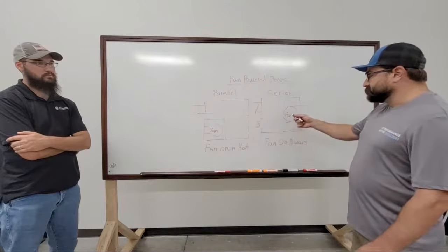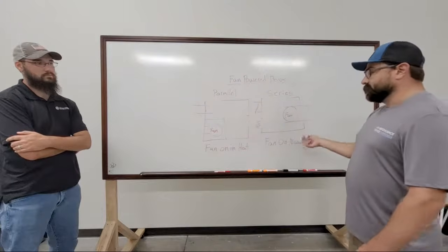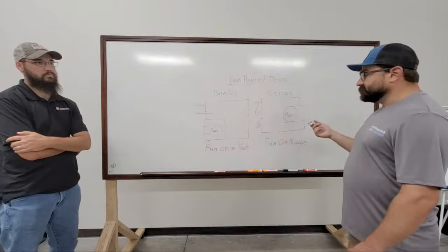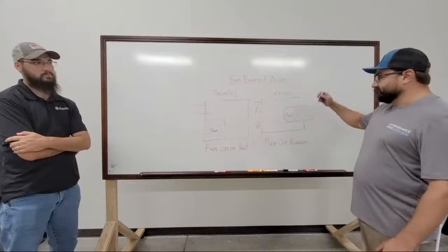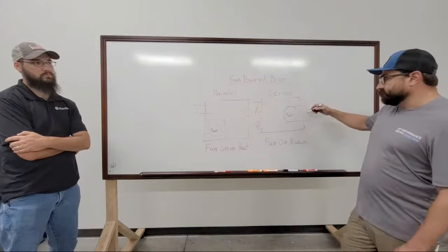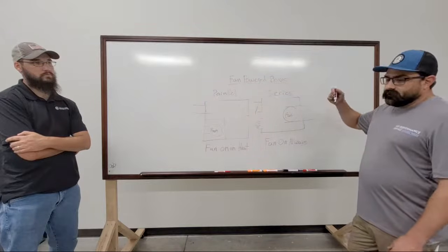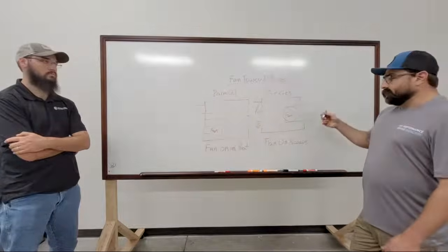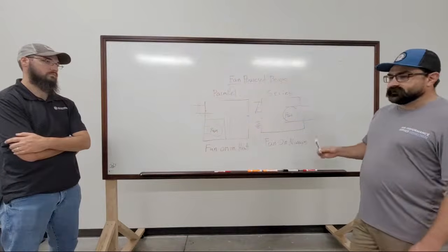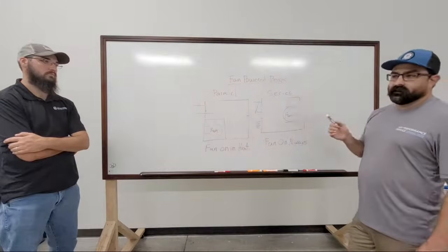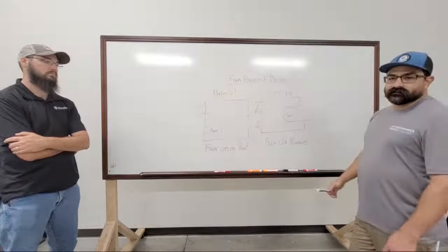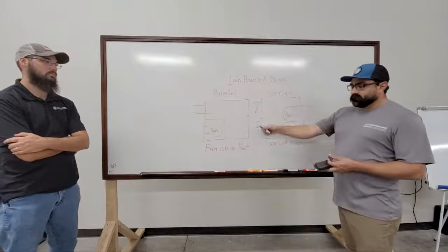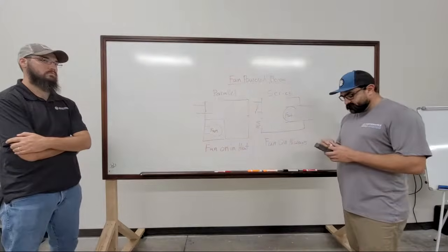Whereas a series box, your fan is always running no matter what. Series boxes are nice because they are constant volume, is another benefit of them. So you don't get that, the fan clicks on, the fan clicks off, customers complain about noise. Anytime you have an open ceiling environment, I definitely recommend series boxes because the noise, you can hear them, they're always running, you don't hear them click on and off like you do a parallel box.